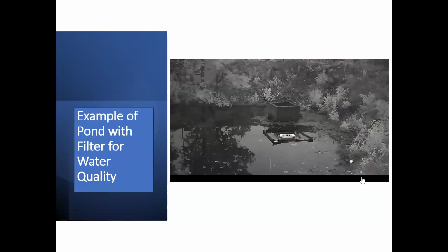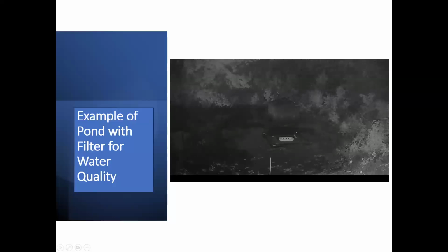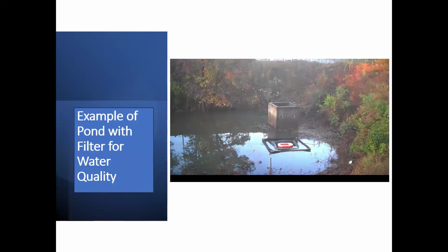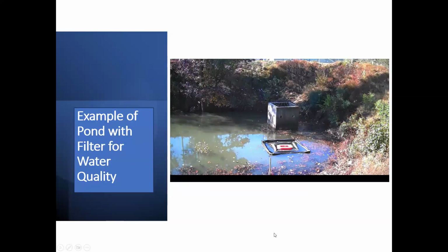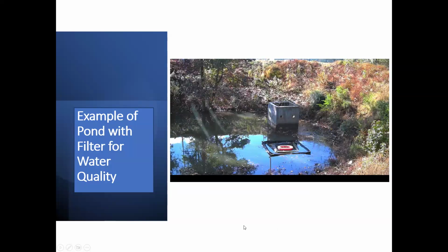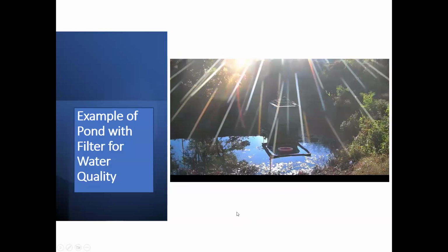Now, we have sized this skimmer to still meet the minimum 24-hour drawdown time of the water quality volume. We haven't gone back and updated the permit to recognize any benefit of the filter. It's just an extra here. We are just using that to drain. And so you can see over time that skimmer slowly draining the pond down, allowing time for sediment to settle. It's also having the benefit of things going through the filter.